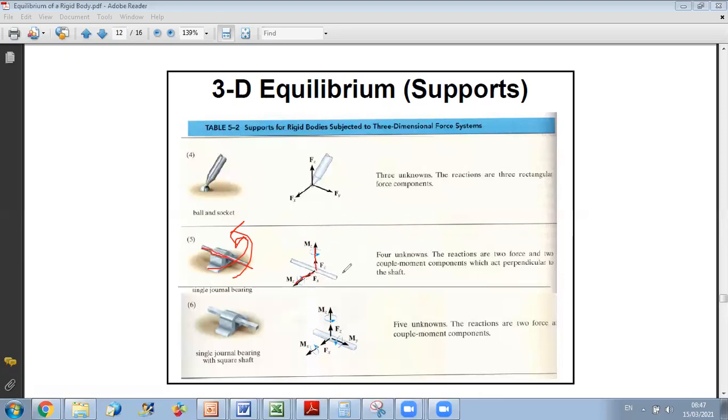Now, concerning the force, from my figure, can I translate the rod along this direction? It seems yes. Because here you have like a hole, you can translate if they don't mention any additional information. If they don't say you have a thrust, or if they don't say that we are blocking translation, then you can move your rod in this direction. So you don't have a force developed along the axis of the rod, but you cannot move it up and you cannot move it in this way.